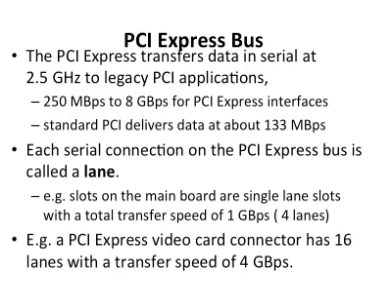So after PCI, people designed the PCI Express bus. Although they share the name PCI, in fact this PCI Express bus transfers data in serial. The PCI bus transfers data in parallel, because you have those 32-bit or 64-bit data buses. PCI Express transfers serial data, but very fast, at 2.5 gigahertz. And for one pair of serial data, transmit and receive, it can support up to 250 megabytes per second.